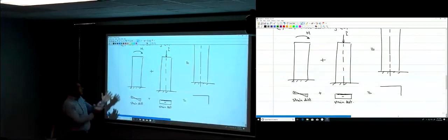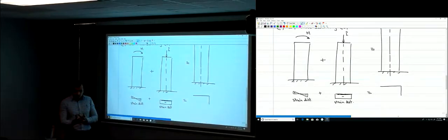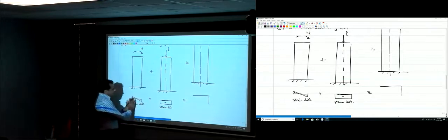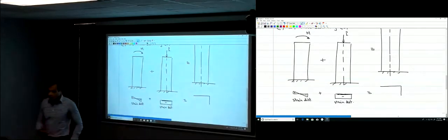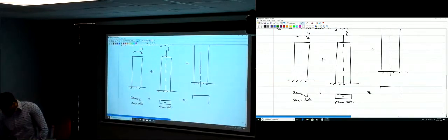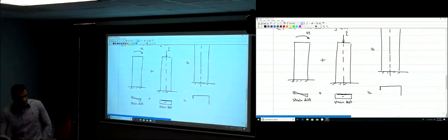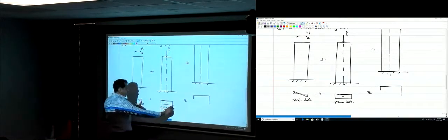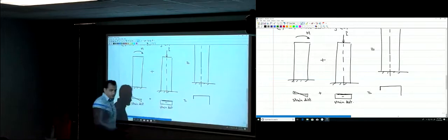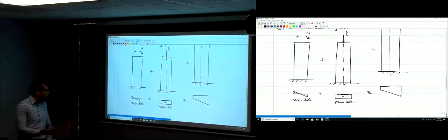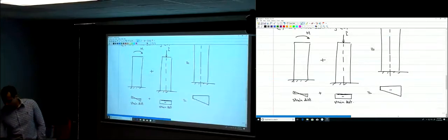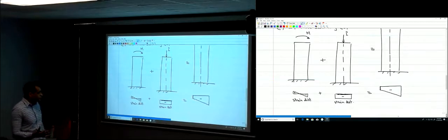In our case here, we said we start with a small bending moment. I mean here that this tensile strain is going to be small compared to the compression strain here. So overall, it would remain negative here. But it's not going to be the same negative value here. This is a very large negative strain. This is a smaller negative strain here. So the strain at failure will look like this. It's all compression. This is the strain distribution. At failure, when will this column fail?